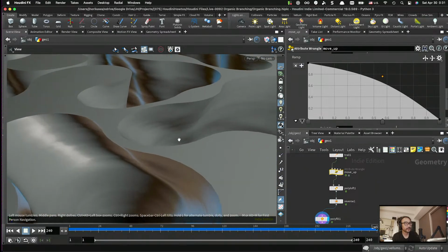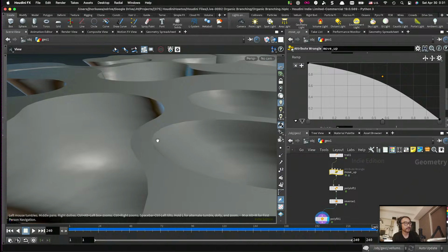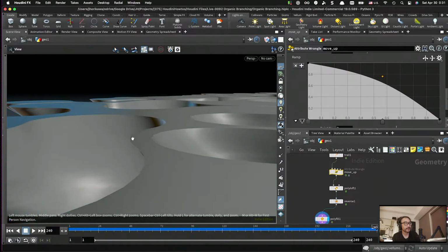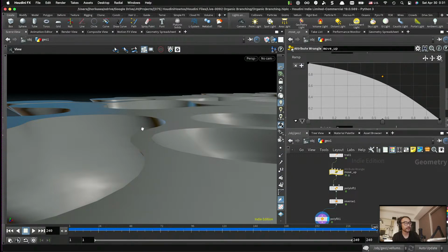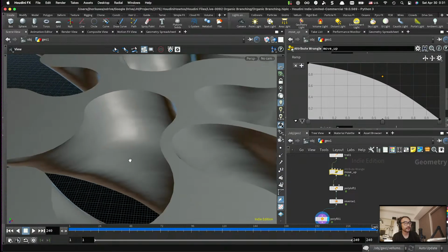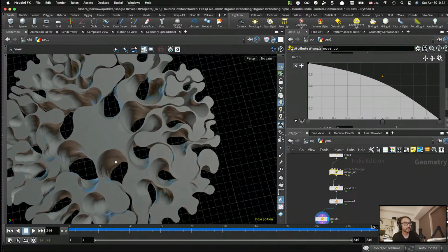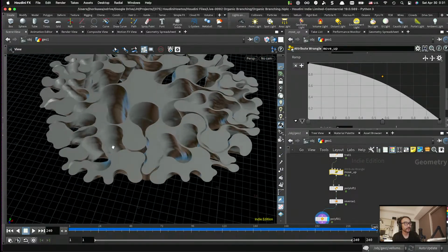But some part like this one, you have really thin edge, really thin width, so you gotta be careful about how much you could bevel. The bevel amount has to be less than half of this width, which is not that much, or the minimum width of this whole thing.